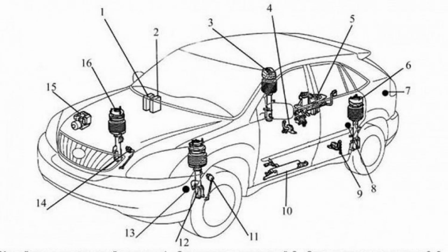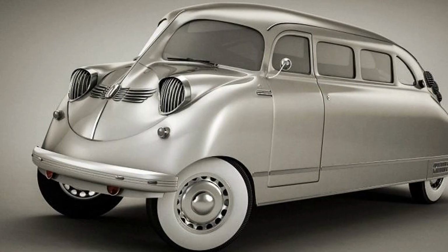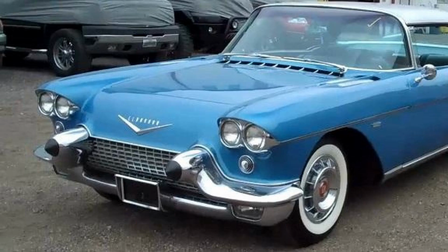Air suspension is not a separate type of car chassis design, as it is realized together with other types of suspension, McPherson, multi-lever suspension, non-split beam, etc. All standard systems can be divided into two types: simple air suspension, in which an air element is installed instead of springs. Adaptive suspension. The chassis uses shock absorbers with variable stiffness. The degree of damping changes depending on road conditions or driver's wishes. Due to its cost, the system is used only on premium segment cars.